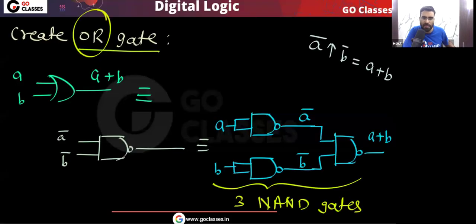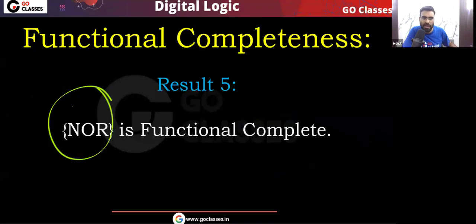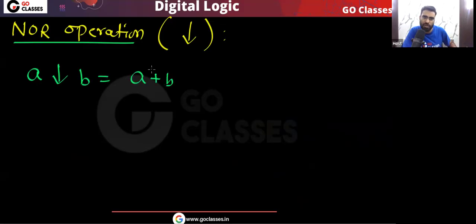Is this clear? Similarly, the next result, that is NOR operation and NOR gate, these are also functionally complete. Okay. Let me tell you. See this NOR operation. First, we will talk about NOR operation, then we will talk about NOR gate. NOR operation, this is the symbol. Now, this is functionally complete, this NOR operation. First of all, what is NOR operation? A nor B. That means first you do OR, then you do complement. So this is your NOR operation.